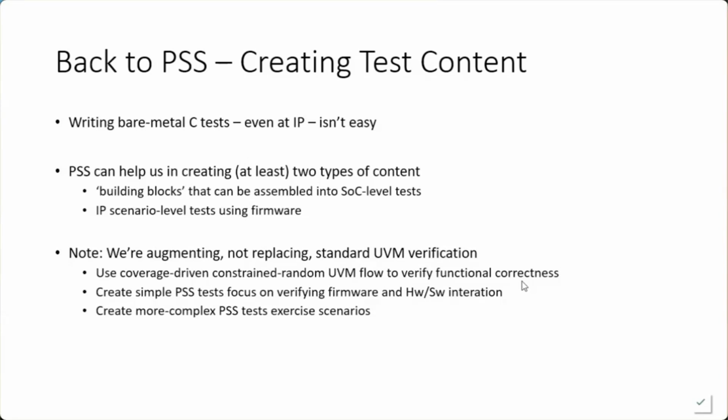Now, it's important, I think, to note here that when we're talking about PSS working together in this process of creating a low-level driver firmware, we're not replacing the UVM as a verification flow. We're still relying on the constrained random coverage-driven UVM flow to verify the functional correctness of the design.